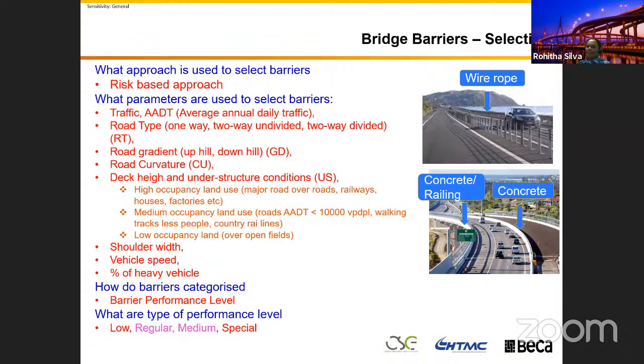So it's all risk elements, and from that we can compare against the actual bridge, the bridge we got when we designed it. When we design for every vehicle, we have a nominated speed on that particular highway. For example, most of the highways we design for 100 kilometers per hour, or at least 90 kilometers per hour. Normal roads we design for 60 kilometers per hour.